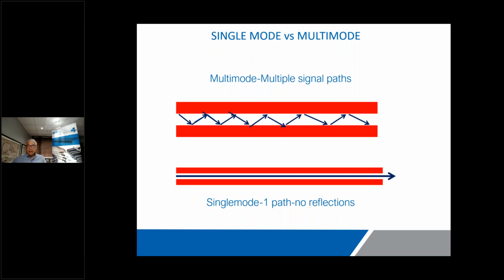That's important to know. And again, one of the themes of the presentation is to make sure that you have all the questions you need to ask and answer before you purchase a fiber, specify a fiber, change or replace a fiber. So the first thing we looked at is: is it single mode or is it multi-mode? And you can see there's a drastic difference in the way that the light travels. The single mode, being the narrow 9 micron, only allows one focused beam of laser light to go straight through the center, giving it incredible performance. The multi-mode, being 5 or 6 times wider, allows multiple paths or modes. So the performance is going to be substantially less.